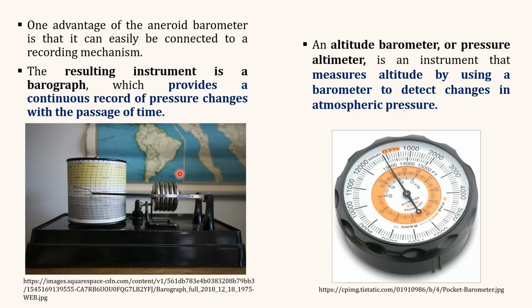When an aneroid barometer is connected to a recording mechanism, the resulting instrument is a barograph, which provides a continuous record of the pressure changes with the passage of time. An aneroid barometer can also be designed to be used as an altitude barometer or pressure altimeter, which is an instrument that measures altitude by using a barometer to detect the changes in atmospheric pressure.